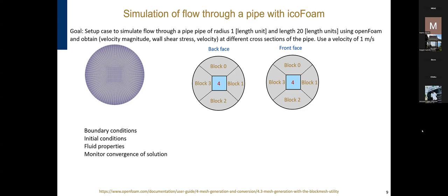If this were a fluid mechanics course, I would have asked you why, but let's not go there. At the walls, you have a no slip condition because you are basically saying the fluid near any wall is not supposed to move.